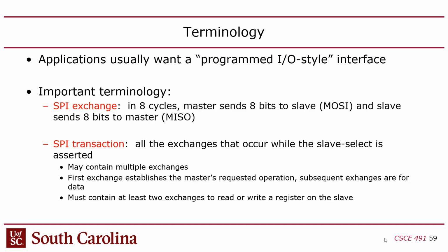As I mentioned, the idea is that the master and slave are supposed to be exchanging 8-bit words, right? The problem is that I have never seen a case where this was needed, ever. It's completely useless. I've never seen a need for true bidirectional exchanges for SPI. For JTAG, yes, but not SPI. So the physical properties of the protocol, which is based on exchanging data, is not really needed, because usually what you're doing with SPI is you're doing transactions.